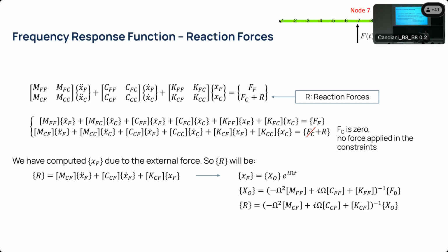and remembering that the derivative of x0 is just i omega times that value. So we can do exactly the same things that we did before and find an expression for the reaction forces, which uses the CF part of our matrices to find the value of the external forces as a function of the free coordinates, which are a function of the input force.